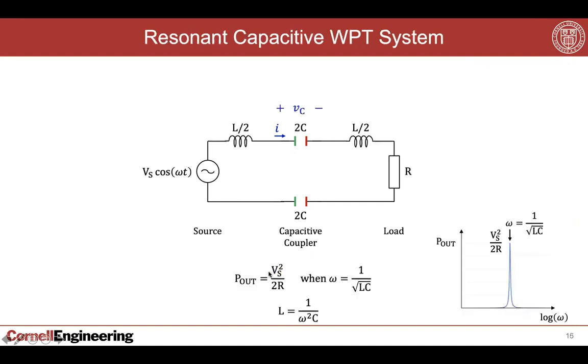And that solution is essentially what Tesla also realized, which is you use resonance. And in resonance, what we're doing is we're taking the reactive impedance that is given by the capacitive coupling, which happens to be a negative reactance, and you cancel that out by adding inductors in series, and those inductors provide positive reactance, and hence the overall net impedance of this path drops down.